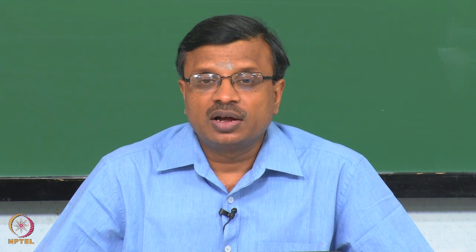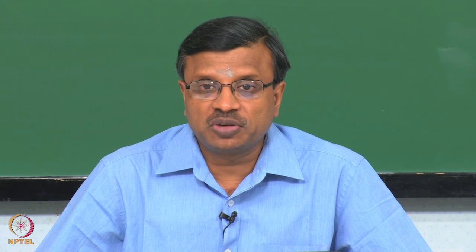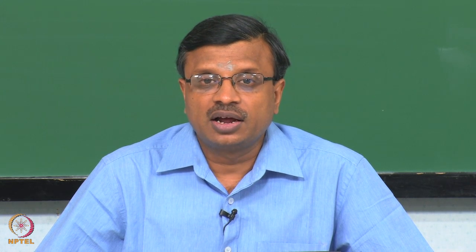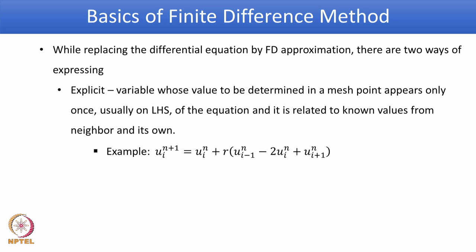Similarly, if you are solving an unsteady equation and you are computing in an iterative procedure, then you have one more index to represent the time integration level. So, for example, for the unsteady momentum equation, u at any nodal location for 2 dimensions is i comma j, and then one more superscript index n to represent that you are doing time integration and you know the value of u at the n-th time level.